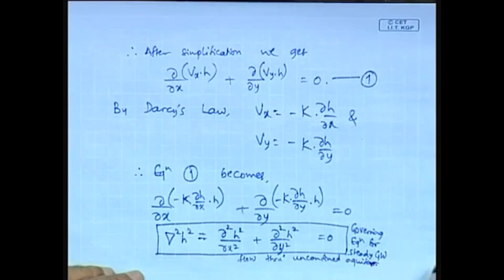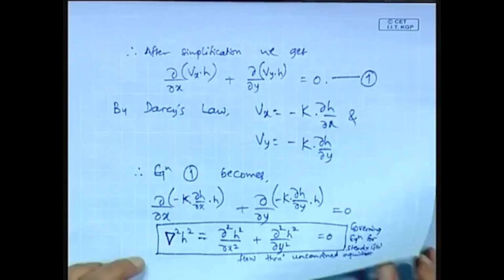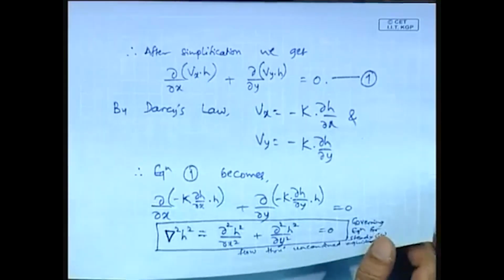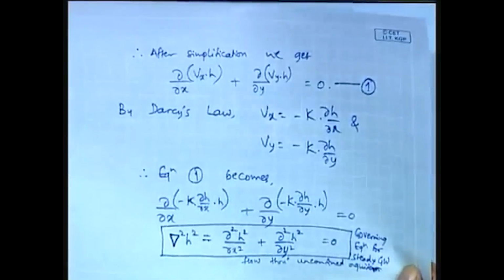Unconfined aquifer. So, this unconfined aquifer for the steady flow satisfies the Laplace equation in h square, whereas the confined aquifer will satisfy the Laplace equation in h, while in case of unconfined aquifer it satisfies the Laplace equation in h square. So, now let us consider the unconfined aquifer,